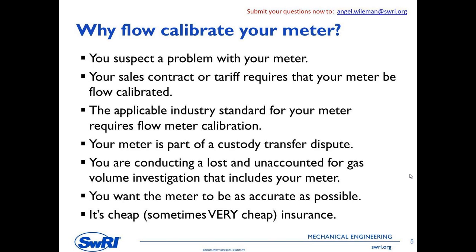Sometimes it's because you think there might be a problem with your meter. You've got a loss unaccounted for that points to a certain meter, and that's what you want to go check out. So that's a good reason to calibrate it. Your tariff may indicate that you have to calibrate the meter. It may reference an industry standard like AGA 7 or AGA 9 for turbine meters or ultrasonic meters that tell you that you have to calibrate a meter to make sure that it's accurate.